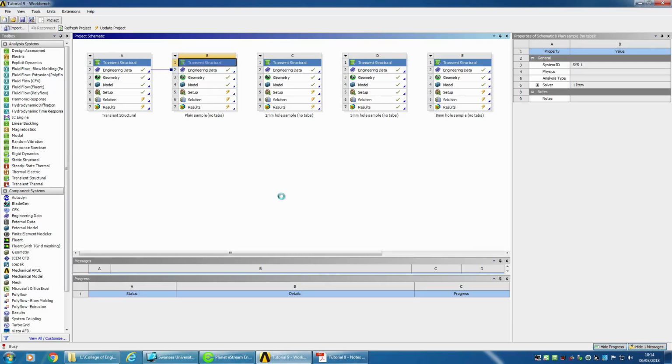First, we're going to look at the engineering data, the database of properties. We're going to have 3 materials defined in there. We're going to do one with just an elastic analysis. Then we're going to do another one with an elastic perfectly plastic analysis. And then another one with an elastic multilinear isotropic hardening rule, which is defined upon experimental data. Experimental data from last year; you guys are going to have to get your own data, but it'll do for now.